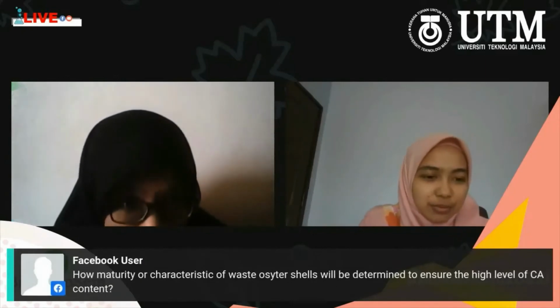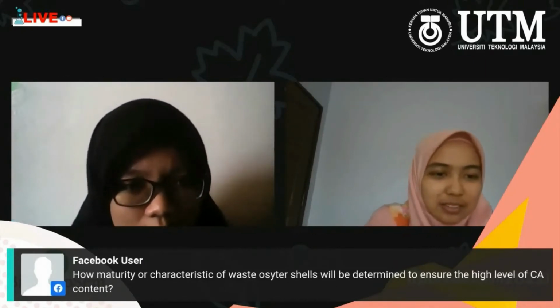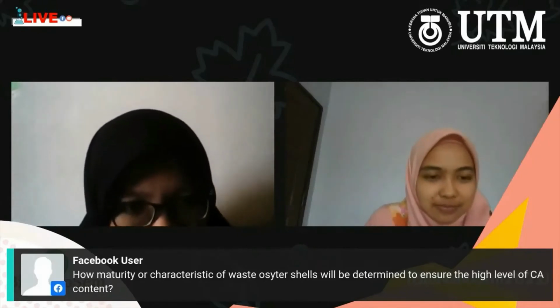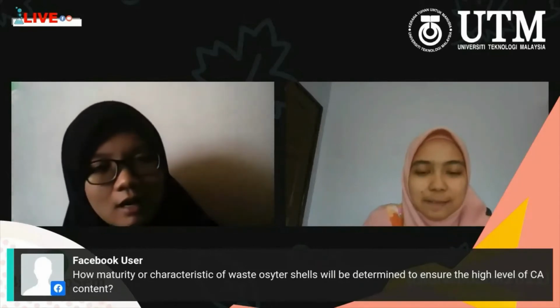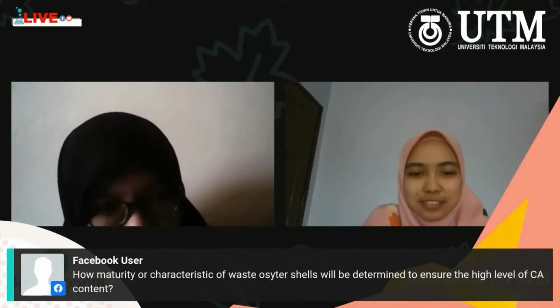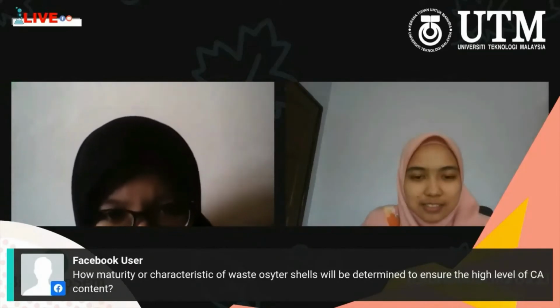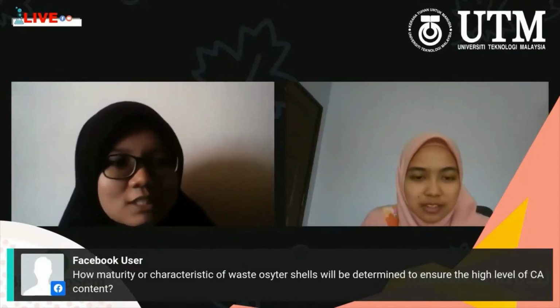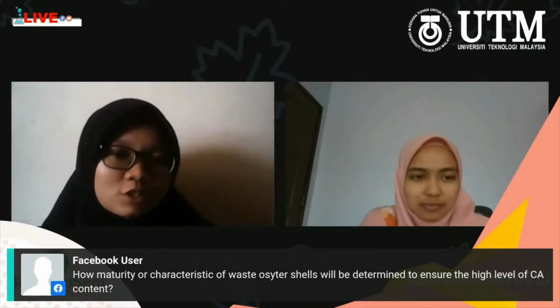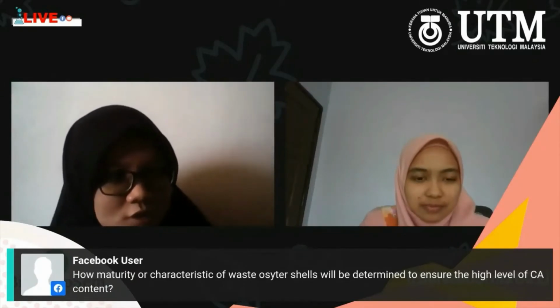There is a question from Facebook: how is the maturity or characteristic of waste oyster shell determined to ensure a high level of calcium content? The level of calcium content is not determined by the maturity of the waste oyster shell. It is determined by the heat treatment process that we perform, because I found that at 1000 degrees, our calcium content is about 99.60%.